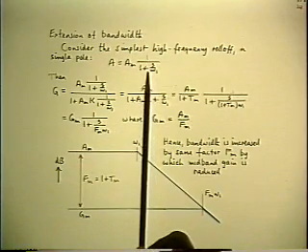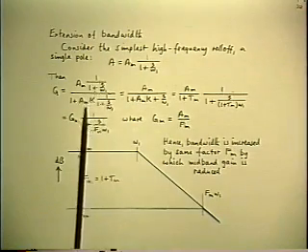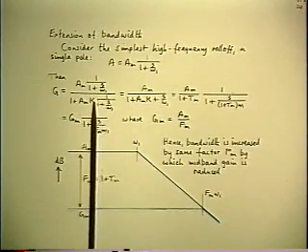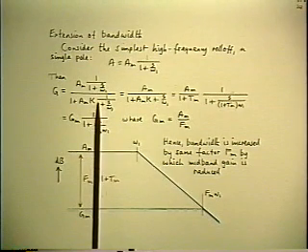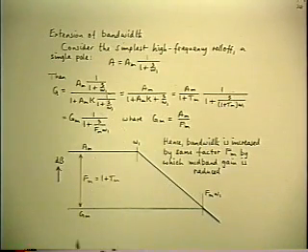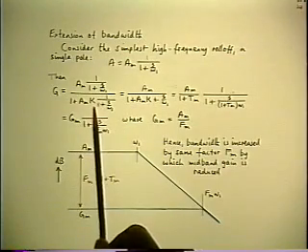What is the closed loop gain G? Well, it's a simple algebraic substitution into A over 1 plus AK. Let's assume for the moment that K is flat. It doesn't have any corner frequencies. Of course, this isn't necessary, but let's keep it simple to begin with. So K is simply a constant.